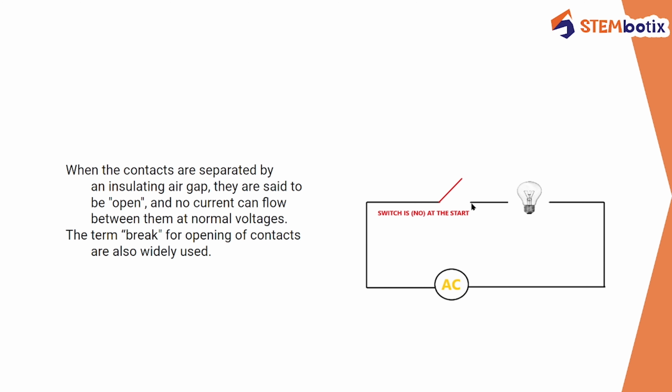So this is how your SPST, SPDT, DPST, DPDT and DIP switch looks like. So from this you can see it is SPST, means single pole. Here will be available only one circuit and the current has only one path to flow through. But in SPDT means it will have only one input circuit. The circuit will be one, but the current have two different paths to flow through. Means from entering from here, it will have two paths, either this way or this way. So it will have two different paths to flow.